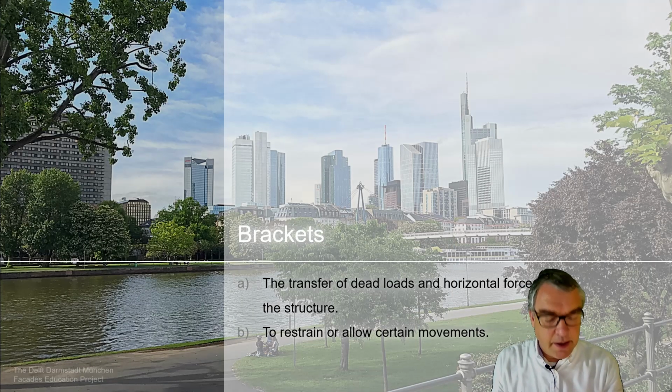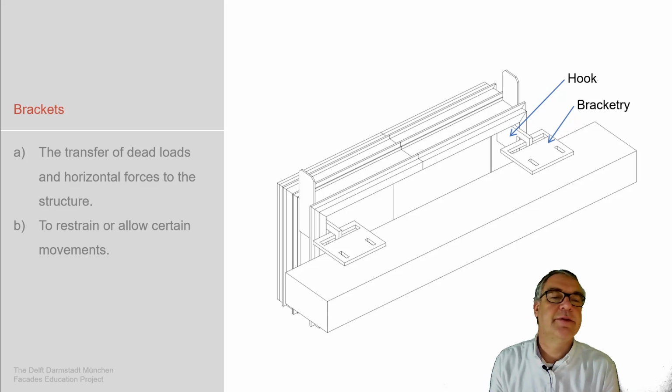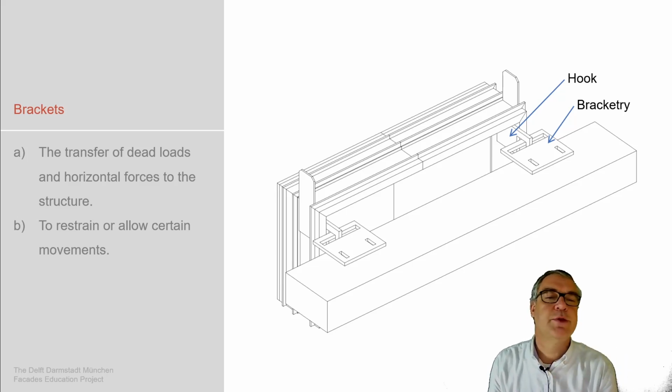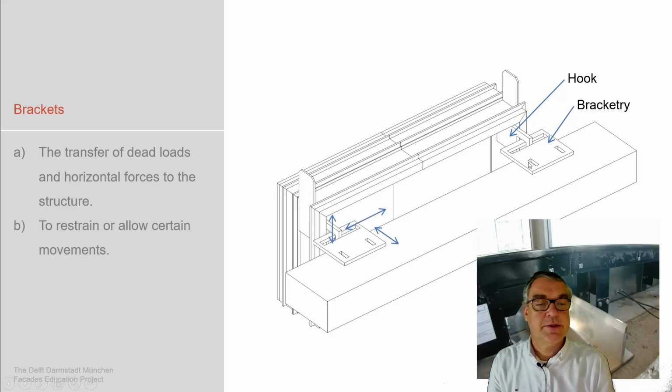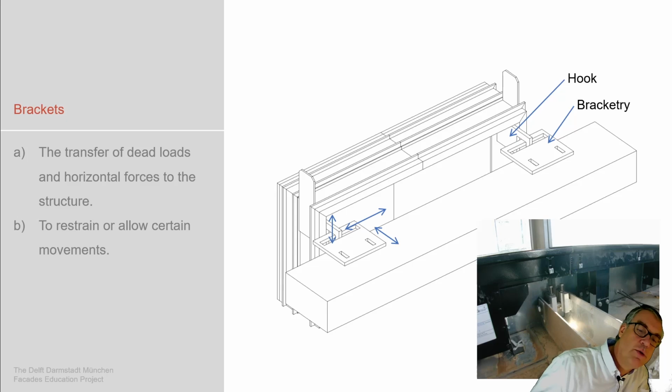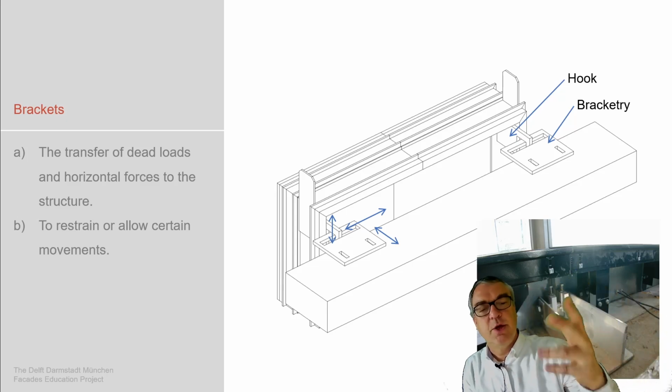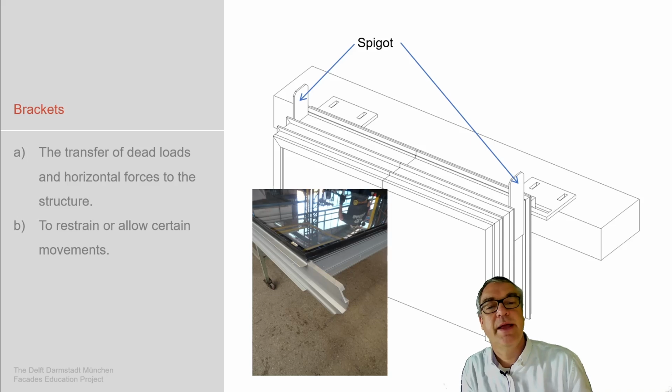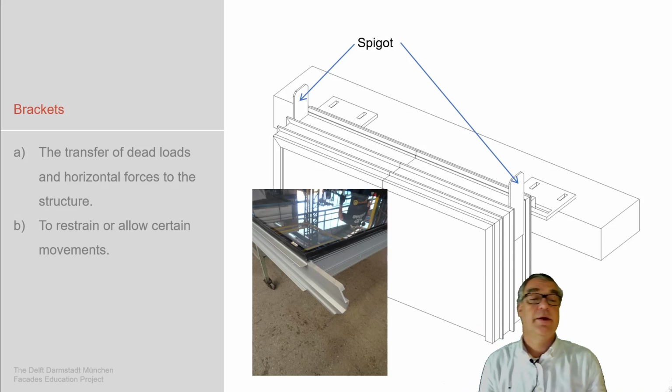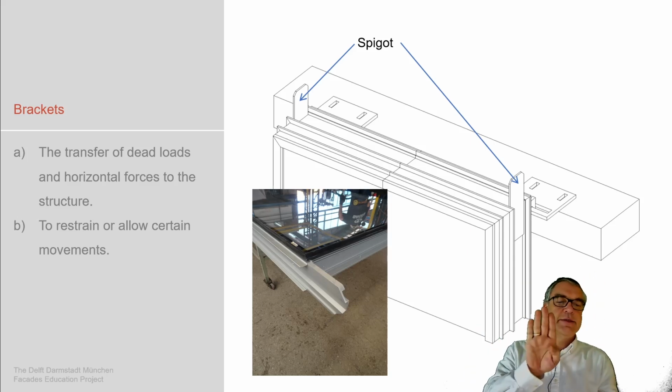These brackets are defined like this. We have this horizontal bracket which allows in all directions the movement, this direction, the hook which needs to be adjusted, and the possibility to adjust it in this direction as one bracket system. This is exactly what I just showed, the bracket which is used for this system as a set. And then there's the need of connecting these unitized facades.